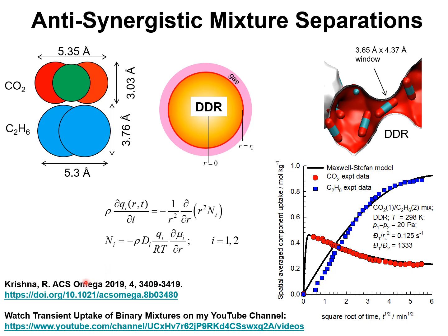Separation of mixtures of CO2 and C2H6 is relevant in the context of natural gas processing. Current technologies for CO2/C2H6 separations use extractive distillation because of azeotrope formation. In my presentation today, I'm going to discuss a different strategy for separating mixtures of CO2 from C2H6, and this